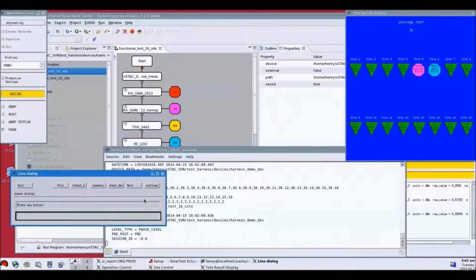We've shown quite a few components that make up TFI. All of these components are built on a TFI framework. The TFI framework provides event reporting, which allows you to synchronize your components with events that come out of SmartTest or even custom events. It also provides uniform access to SmartTest APIs, such as the TPI, CPI, and HVM API.